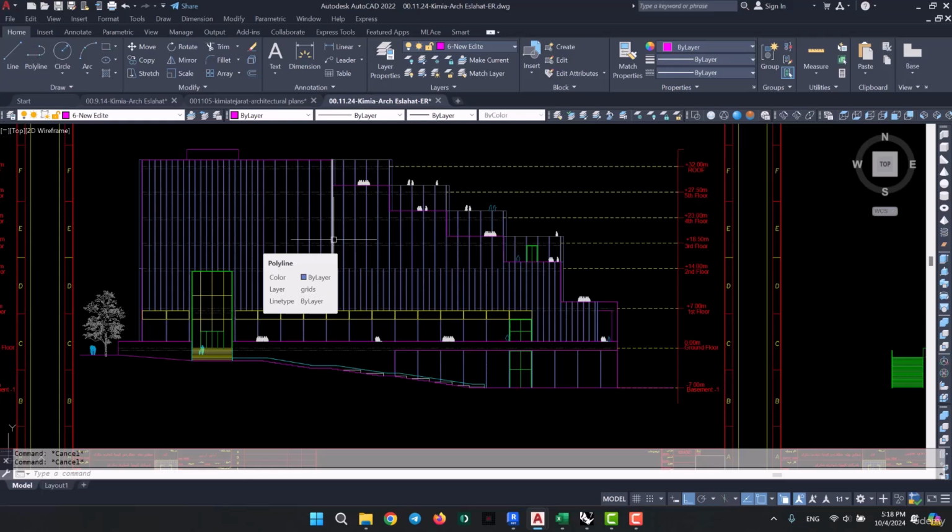And for instance, if you import this elevation into your project and see that your drawing differs from it, then you'll need to check two things. One is whether you've drawn correctly or not, so then you'll have to double check the plan and see if the modeling error was from you. But if that weren't the case, then it would mean that the plan has some issues and it needs to be reported. So you'll have to discuss this with your client and see which one should be prioritized and whether you should follow along the demonstrations in the elevation for your modeling, or if you should go based on the position of the mullions in the plan. So those need to be checked, along with anything else that you're not sure about.